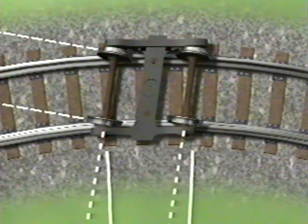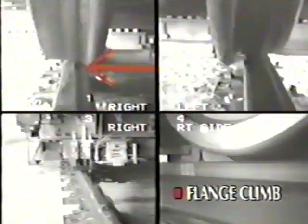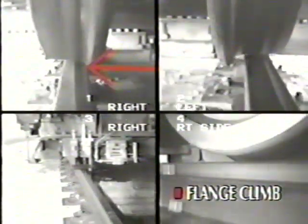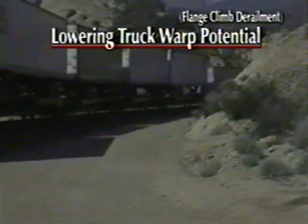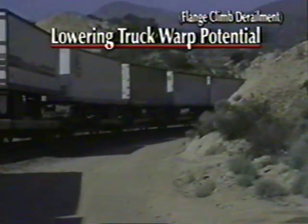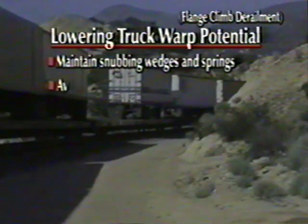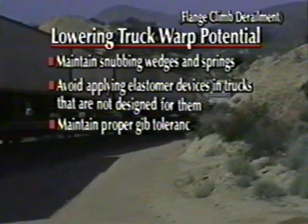As stated before, lateral forces generated by a wheel set running at a large angle of attack increase with the wheel rail friction. Most flange climb derailments are associated with extremely dry, low rail running surfaces. Some railroads are experimenting with lubrication on the running surface of the rail, especially the low rail, to reduce the effect of these large lateral forces. Let's review the efforts that improve truck warp resistance, like maintaining the snubbing wedges and springs, applying elastomer devices to only the truck designs where they are intended, and maintaining proper gib tolerances.